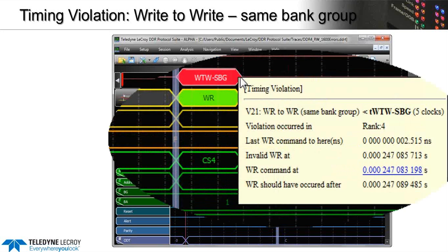own measurements. But verifying the compliance at the JEDEC timing table level is really just one part of the feature set here. We have users right now doing DDR4 bring-up testing, functional testing, debugging real problems at power on. And basically, you can do all this at a much lower cost than using a logic analyzer by using the LeCroy DDR bus analyzer.